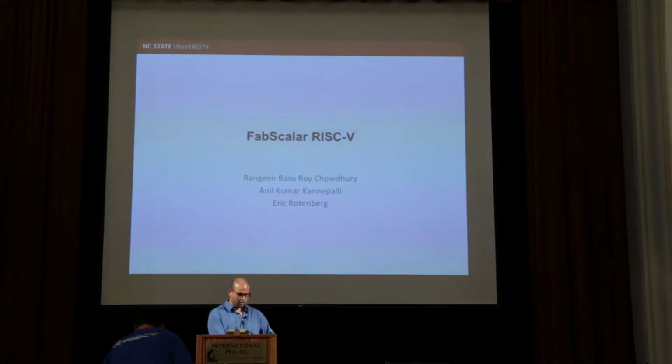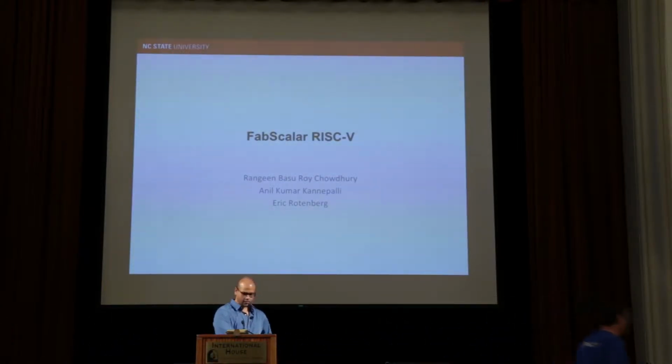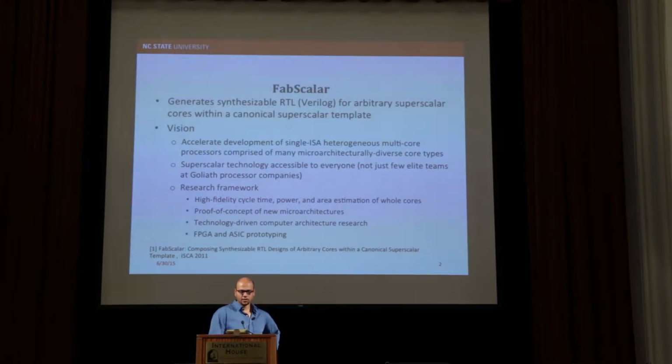And I'll be talking about the FabScalar RISC-V version that we are going to release in a few days. So what is FabScalar? FabScalar is a tool that lets you generate synthesizable RTL, Verilog or SystemVerilog, for arbitrary superscalar core configurations within a canonical pipeline. So these are out-of-order cores, and the vision behind FabScalar was to accelerate the development of single-ISA heterogeneous multicores, which was a research topic our group was pursuing